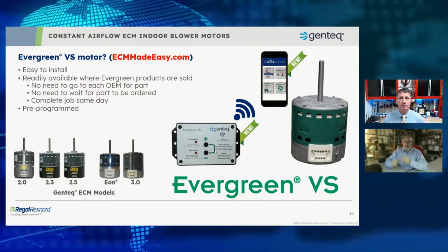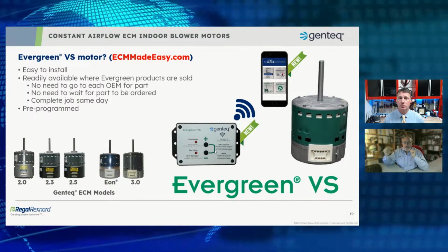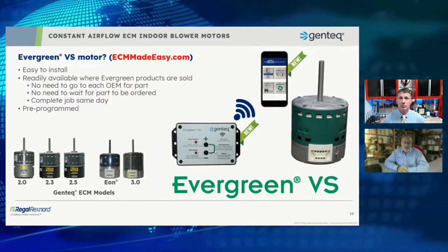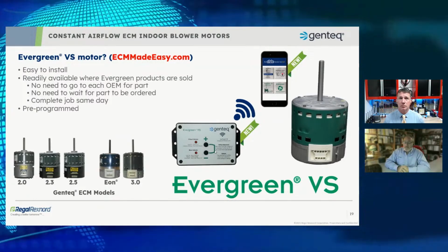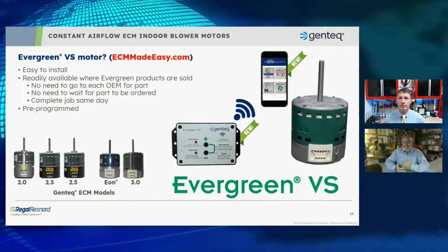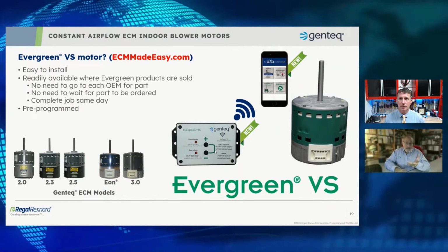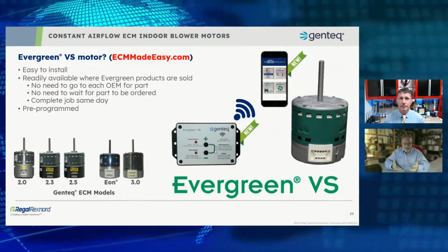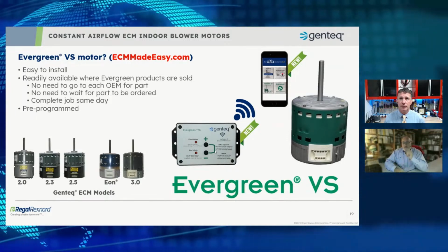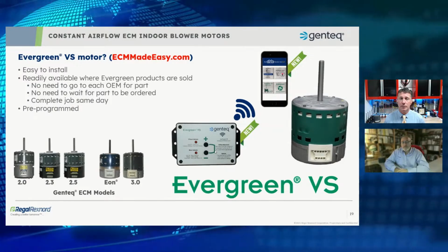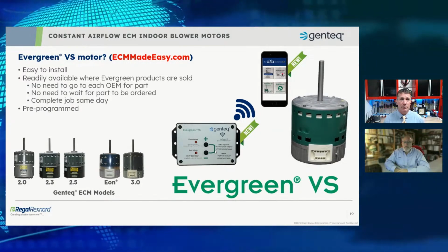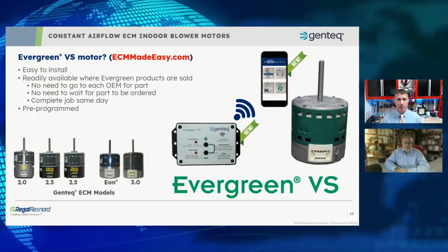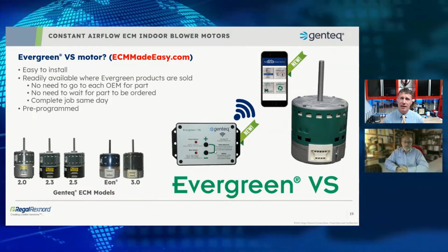Yeah. So we moved the functions that the technicians who want to really tune it in to the app, and we made them more user-friendly so that they can reduce their time on the job if they choose to do that. But I'm also hoping it encourages technicians who didn't check airflow before because of the time excuse. Absolutely. Can't solve the tool excuse because you're always going to need the tools for either measuring air or temperature. But I can reduce the time excuse by having a device that allows you to adjust it in real time. Yeah, absolutely. While that thing's ramping up, you can be picking up tools and getting things organized and make your final adjustments, or pick up and clean up some more and then recheck it again. Yeah, that's a fantastic way to look at that.